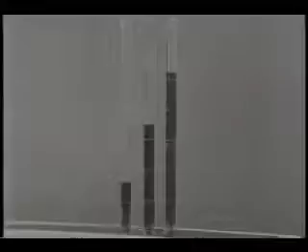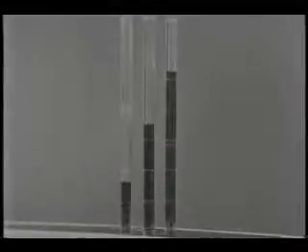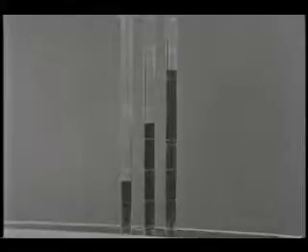This tall tube shows the stagnation pressure in the large upstream settling tank. The difference between this stagnation pressure and the static pressure at the upstream tubes gives a dynamic pressure of about 11 inches of water. At the middle of the bend, there is a pressure difference normal to the streamlines of about 3.5 inches of water. This is close to what we would predict using Euler's equation for the normal pressure gradient.